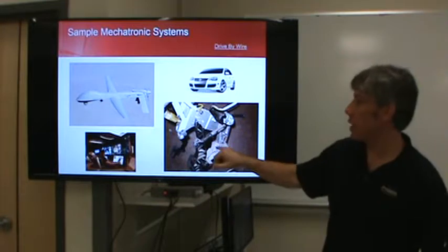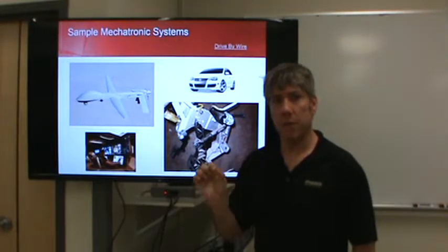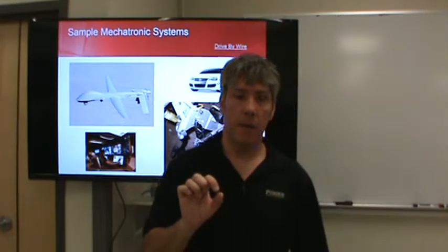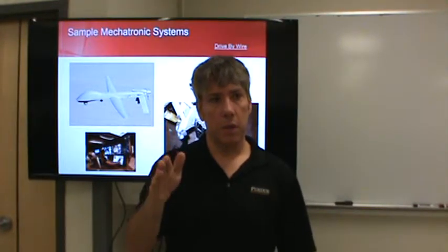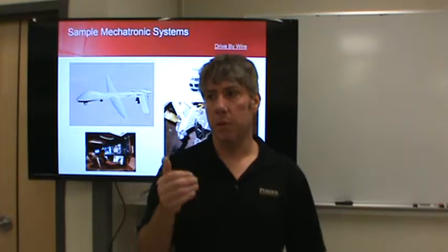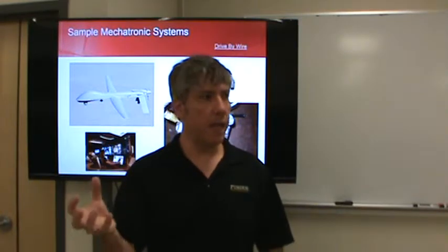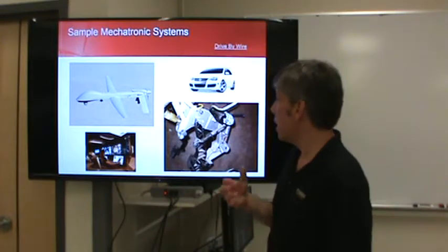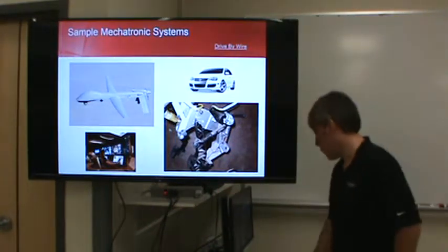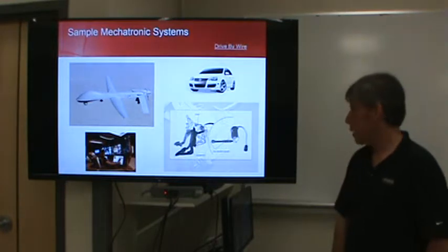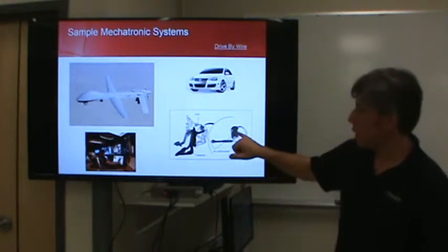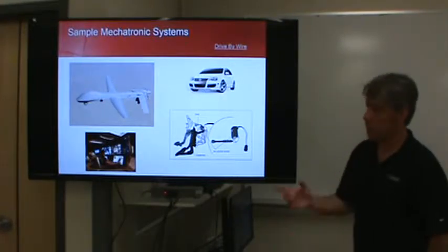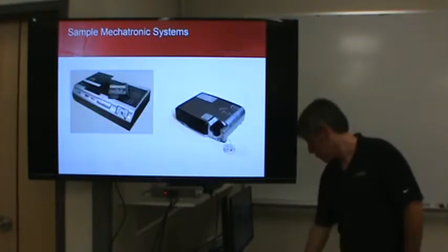Why is this mechatronic? That injector pump has to inject a very precise quantity of fuel into the cylinder, okay? Not only that, but the throttle position that allows air in has to be fairly precise. So the mechanical side that the computer is controlling is precise. There's a lot of precision there. And so that qualifies this, in my opinion, as a mechatronic system. And here's a little more detail where you can see the actuator separated from the accelerator, so you can see the sensor that's determining the accelerator position.